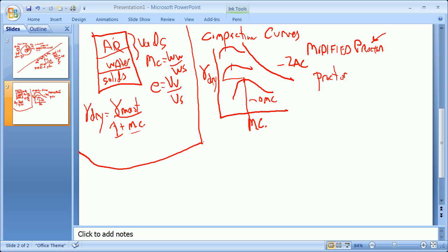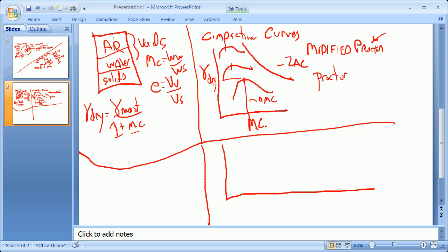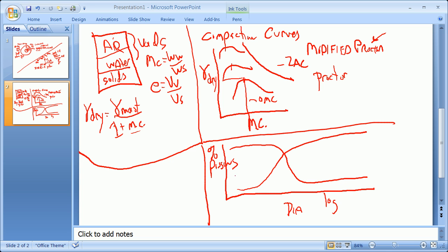So that concept. Still going back or forward, we had another graph in terms of grain distribution size, a soil grain distribution size or an aggregate grain distribution size. It was percent passing versus diameter on a log scale. And so we'll have a curve that looks either something like that or like that, depending on which way your coordinates go. There's numbers that describe this curve, but something with a long shape is well graded, lots of different sizes. Something with a sharp shape has more sizes of one particular, in other words, something like this has a lot of one size shape. So this was a gradation curve. So we're now talking about curves where percent passing or diameter, you realize that these things have units. So in this case, moisture content unitless, dry unit weight has units of weight over volume.